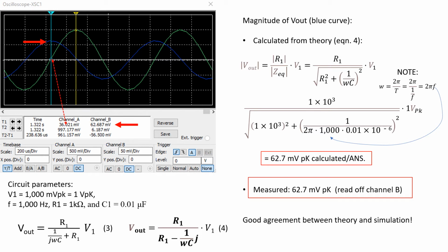Now, channel A data begins with the value of the green curve at time t1 captured on the yellow trace. This value is approximately 36 millivolts. Now, on the graph, the green curve appears almost 0 at the time t1 cursor. And this makes sense since each division for the green curve is 500 millivolts.